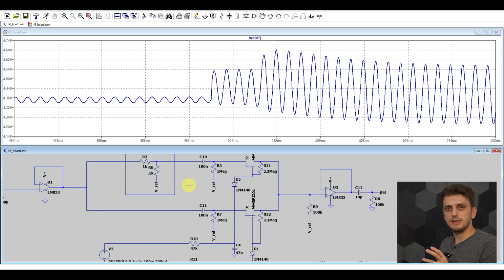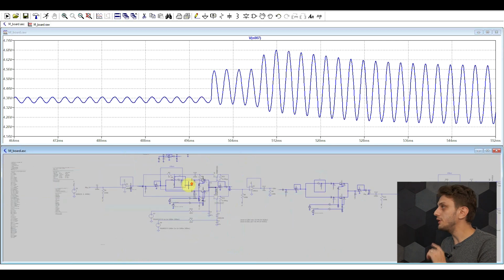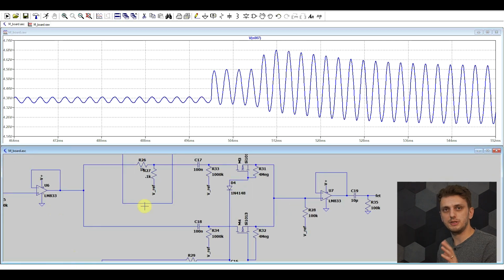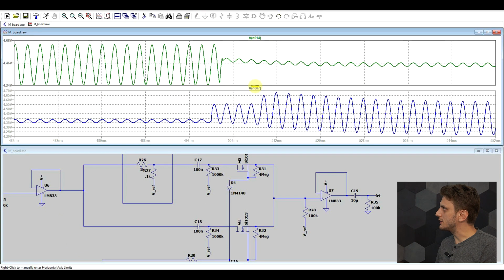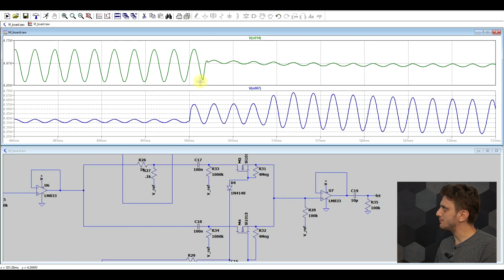On the other hand, if we look at the same thing with the MOSFET circuitry, here we have the exact same input-output signals, everything is the same, it's just the transistors that are different. And if we look at the transition here, well, it's inverted because of the way the transistors work. So we're going from the unaffected signal to the affected signal, but the transition is extremely sharp. We see that the transition is this glitch, really, that happens in between the two signals.